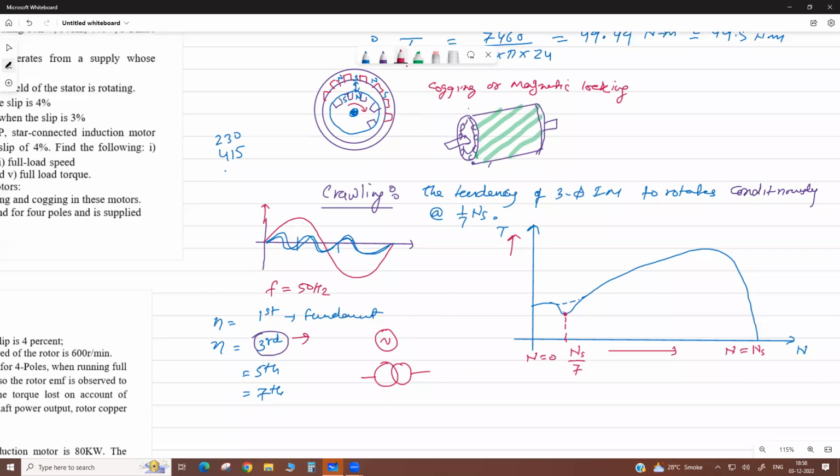Okay. So actually, they have a core, a magnetizing core. So you know the BH curve. There is a non-linearity. It saturates. So due to the non-linearity of the BH curve, it produces the harmonic. So your transformer and this alternator itself generate the harmonic.